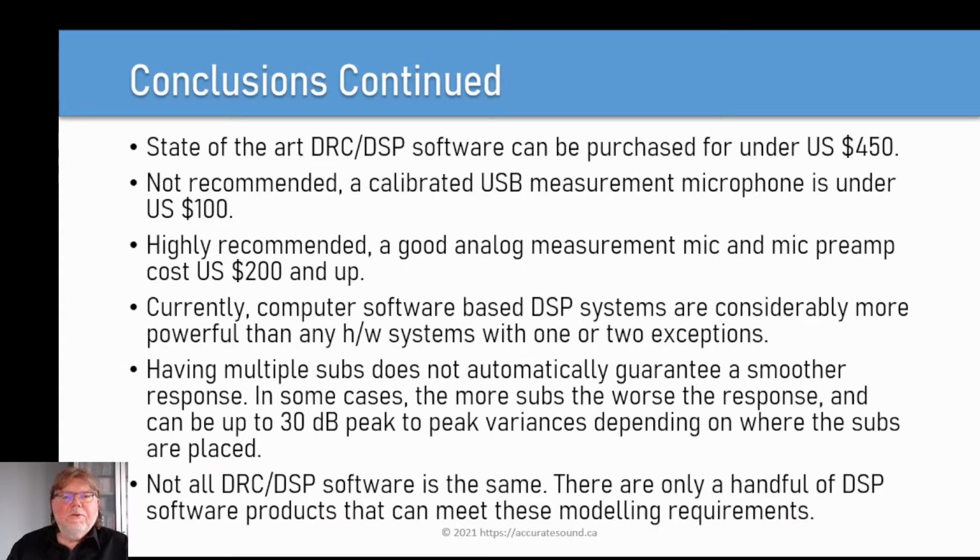Multiple subs generally are a good thing. However, it does not automatically guarantee a smooth response. Even if you have 4 subs set up perfectly, you'll still get around 20 dB of peak-to-peak variation in the low-frequency response due to room resonances. There's just no way around it. So DSP is still required. But if the subs are complementary, a very smooth response can be achieved.